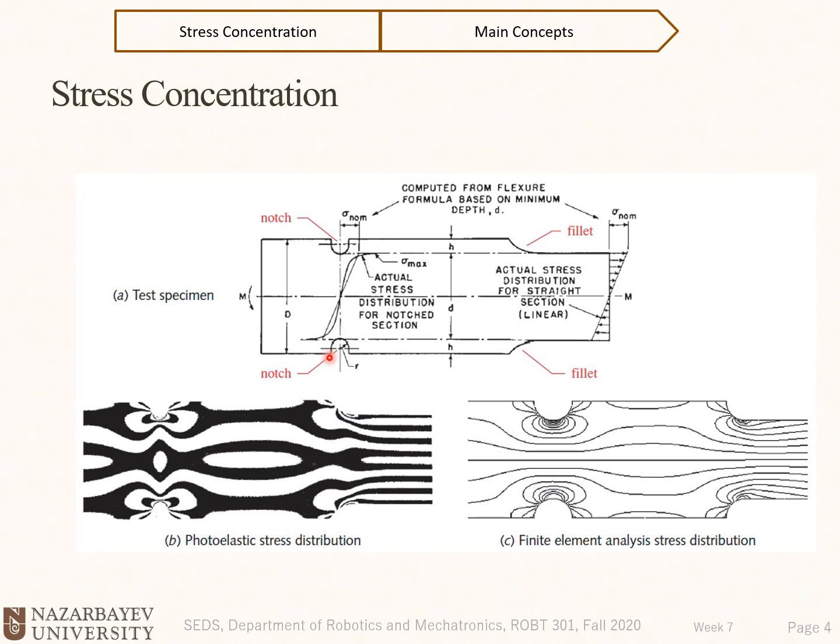But these shapes are necessary to install other mechanical components. We want to install, for example, gears, we want to install bearings, we want to have a key slot, and we see that also the key slot creates stress concentration. And we see what is the effect of these type of abrupt changes in the cross-sectional area. So we could say that these changes create a stress concentration.